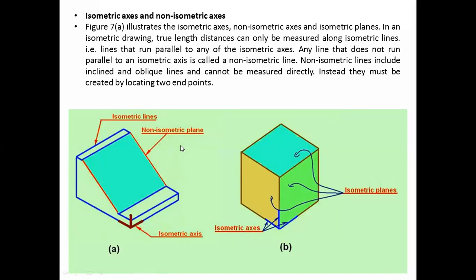Now this figure shows isometric axes. Which are those? It can be asked which are the isometric axes, or what are the angles between isometric axes. Then you should know the angles between the respective isometric axes. What are the angles? 90. Yes, you may tend to say 120, but it is not 120. That is the angle between the three lines along which we draw isometric.